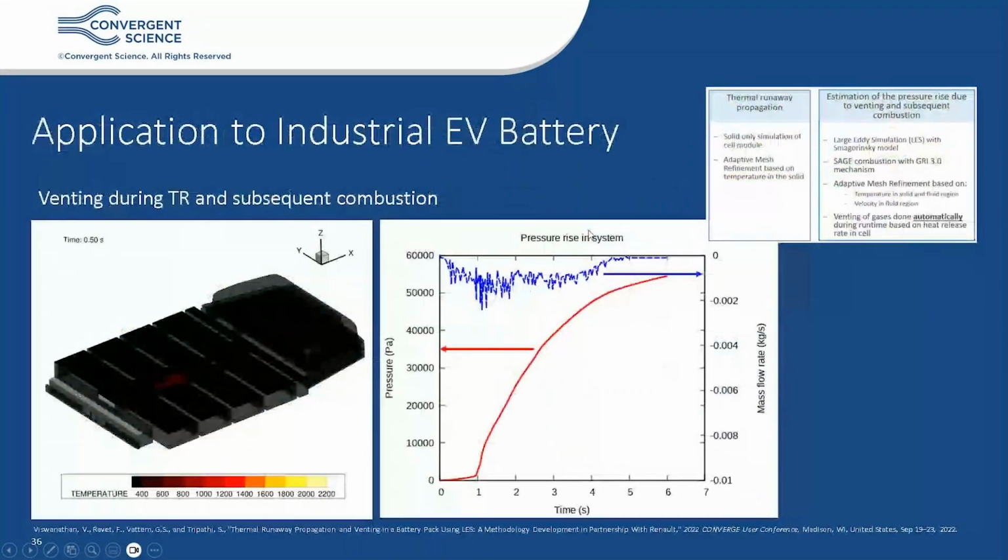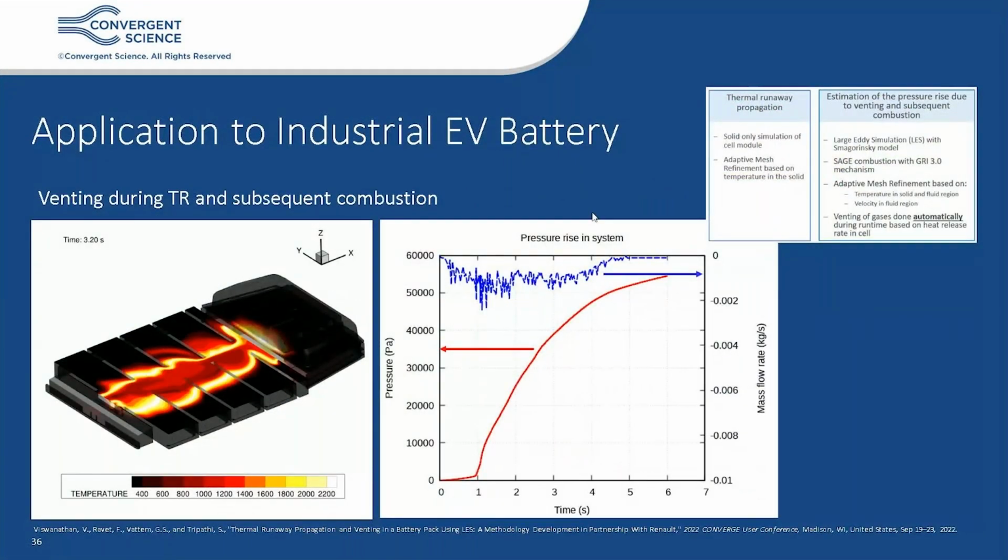An example applied to an industrial EV battery pack from Renault, venting inside a full-size EV battery pack. Again, thermal runaway inside the solid using our calibrated reaction mechanisms, solid-to-solid thermal runaway propagation, and venting of the gases was coupled based on heat release within individual cells.